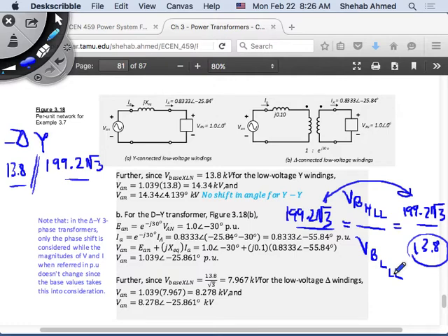Now I would like to solve my single phase equivalent circuit. That has to have all the quantities in single phase after transforming to a star connection, right? Because for me to convert delta to single phase, I have to convert it to a star. So what do you do? We do the same thing: a fictitious star connected to the delta. Remember that trick we talked about?